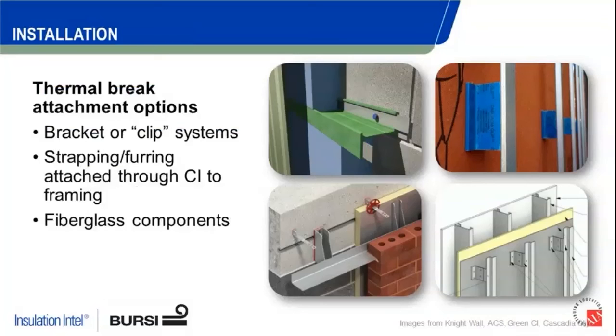Now, we have this slide in here because we typically get a lot of questions about the various attachment methods that can be used with some of the products we just talked about. So we've got various options out there, some of the more common attachment methods on the market that can function as a thermal break. Bracketed clip systems, I think you'd see there, some traditional Z-girt profiles that are now made fully out of fiberglass. And back to the clipped or bracketed systems, you see that brick ledge and your traditional Z-girt functioning there on the bottom right.